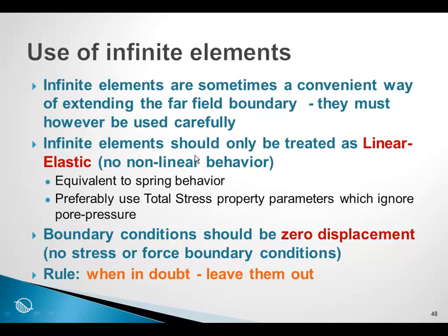This is not totally necessary. We could use effective drained stress parameters in the far field and make use of pore water pressures, but there would be no change in the pore water pressure in the far field infinite elements.